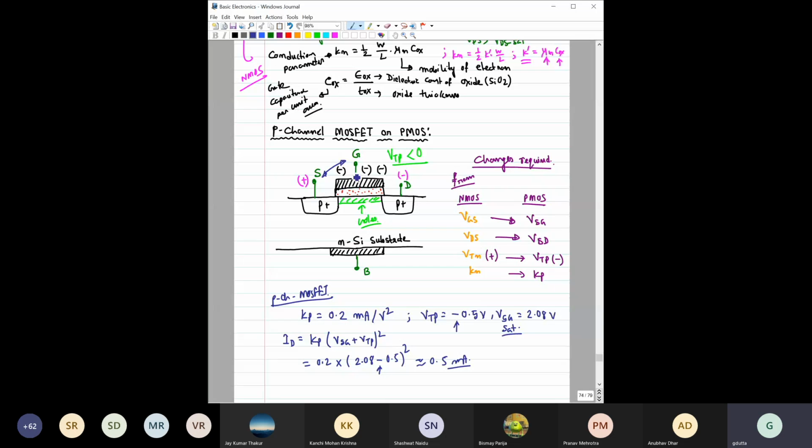So you know that up to the threshold voltage, there will be no channel, no current, right? Then as you increase it beyond the threshold voltage, only then will current flow, right? So the overdrive would actually be the difference between this gate voltage and the threshold voltage. So it will always be the difference between these voltages.